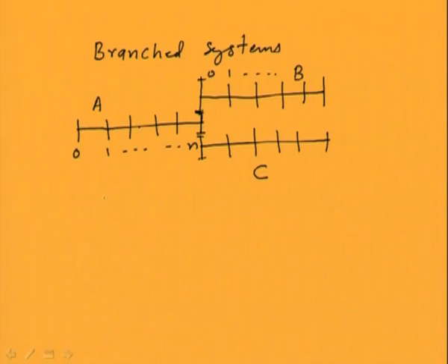So as I told, we will be using the transfer matrix method, and we already analyzed the transfer matrix method for a particular branch. When there is a single shaft, we can write the state vector for that particular case like this. Let us say this is branch A. This state vector corresponds to the nth disk here, and let us say A is the corresponding overall transfer matrix, and this is the state vector at the beginning of branch A.